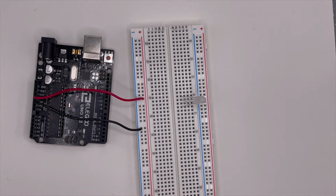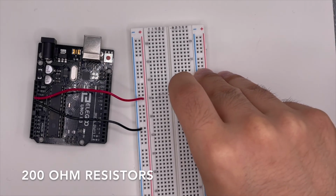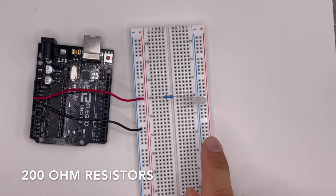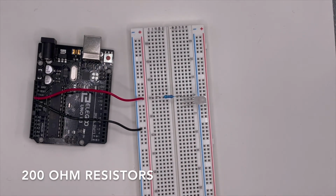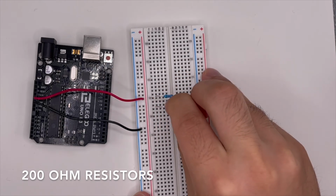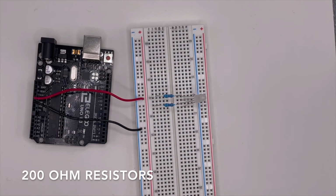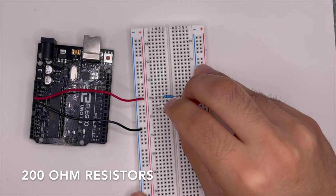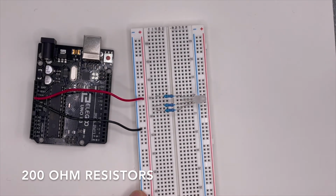Now, we also need to have resistors between the LED pins and the Arduino board. So let's place resistors on the non-ground pins, as you can see here. And we know that this one is the longest ground pin, so we will not be placing resistors on that. Skip one, place a resistor there. And the next one, another resistor here. Make sure that's bridging the gap between the breadboard.